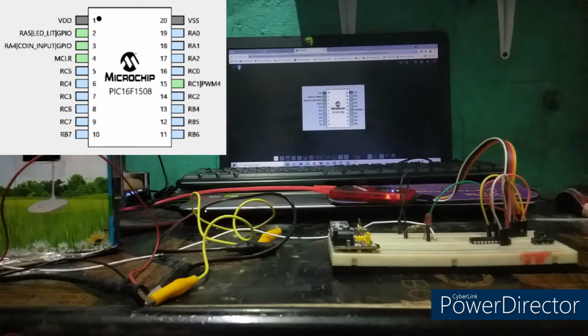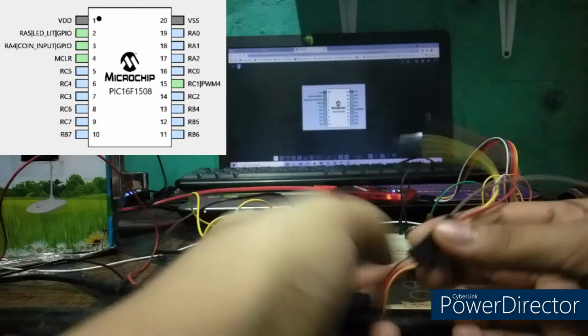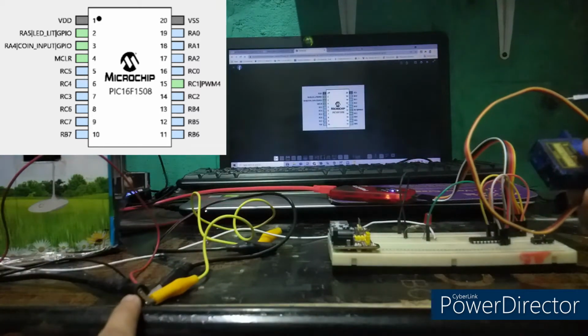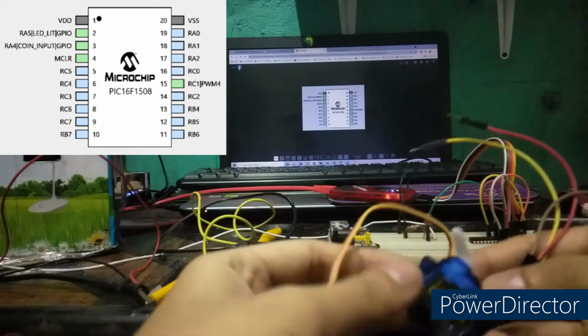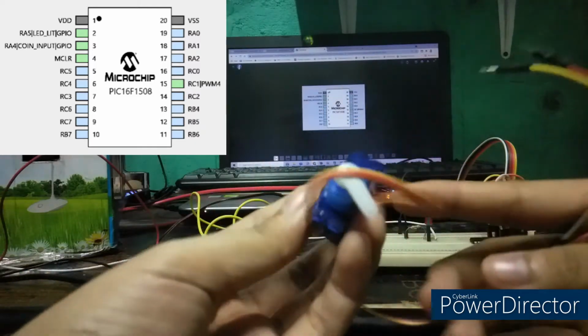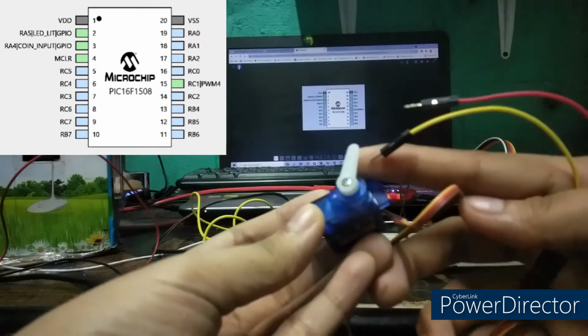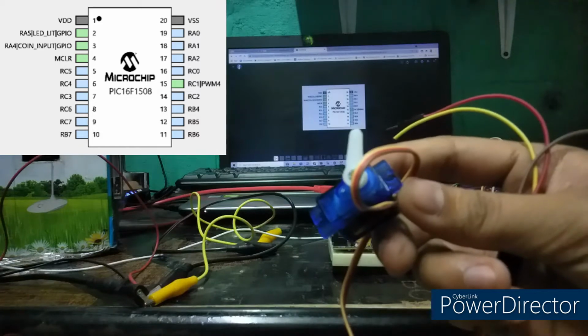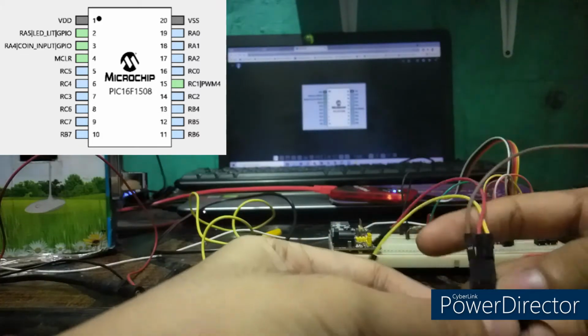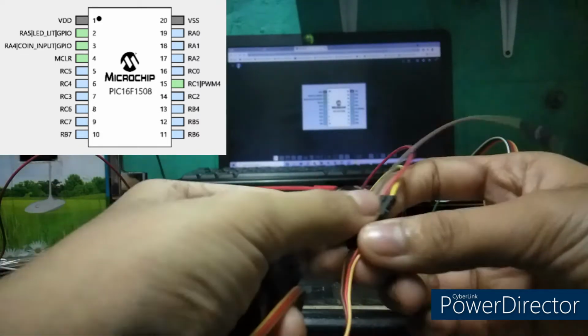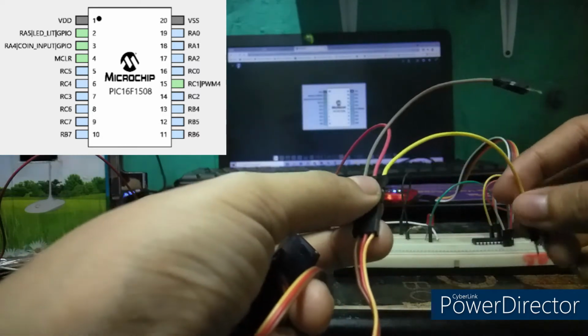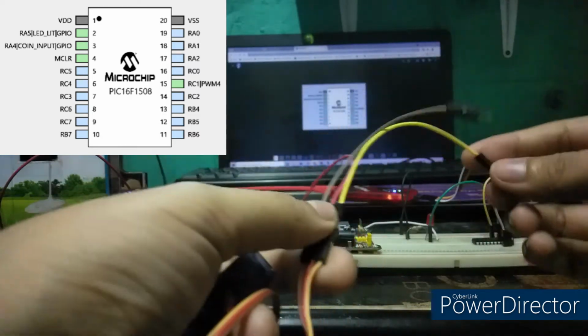Now to show you how the circuit is constructed with our 12 volts coin acceptor and our servo motor. Also we will be using alligator clips and a DC jack as our improvised 12 volts voltage supply. For our servo motor, this is the blade, which we connected already using our screw. For the connection, this yellow wire here will be our connection to our IC. Let's connect this to pin number 15 of the IC, which is the pulse width modulation 4.